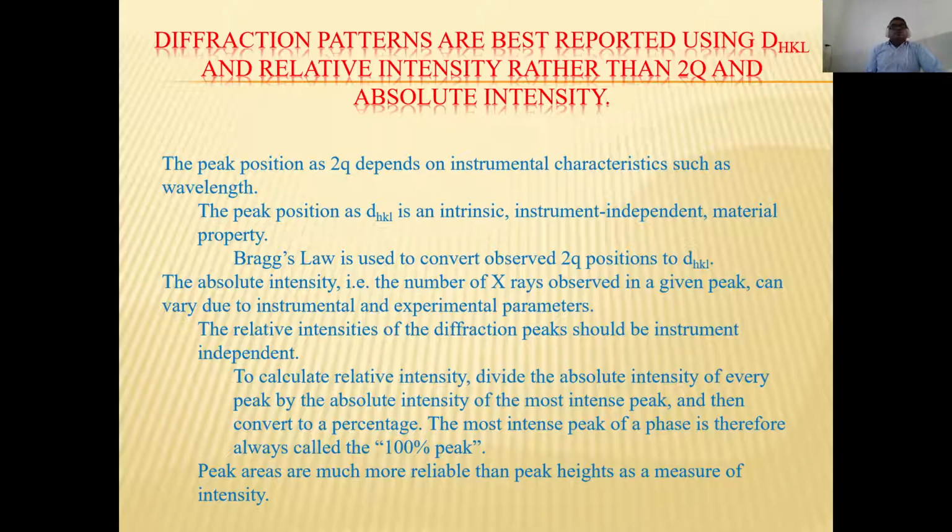The peak position of 2 theta depends on instrumental characteristics such as wavelength. The peak position as d(hkl) is an intrinsic, instrument independent material property. Bragg's law is used to convert observed 2 theta position to d(hkl).